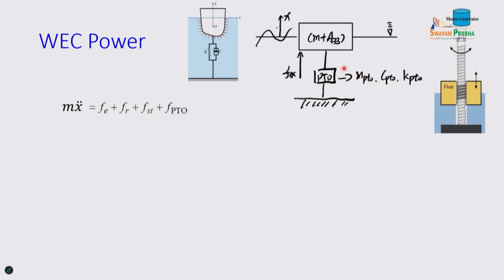Okay, so now we look into wave power, right? So you think about wave energy converter. There are three figures, right? You move up and down, and then you have PTO damping and PTO stiffness. Now you look at how you implement it. Then you may put this on the seabed. You have a floater buoy move up and down. When the floater buoy moves up and down, then you drive a ball screw, right? And the ball screw drives a generator. That is one way to implement that.